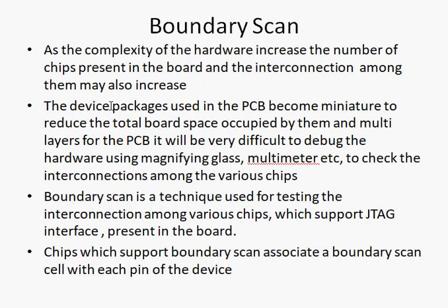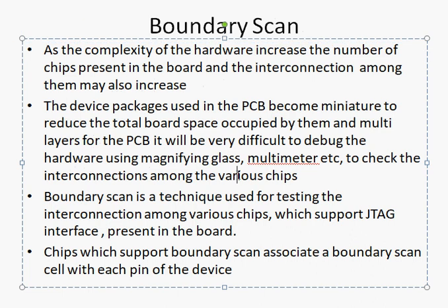Okay, and the last topic is boundary scan. So why do you prefer this boundary scan? Boundary scan is a concept which will be used when you're using integrated circuits. Assume that you have a motherboard with many ICs, integrated circuits, and these integrated circuits need to communicate with each other.